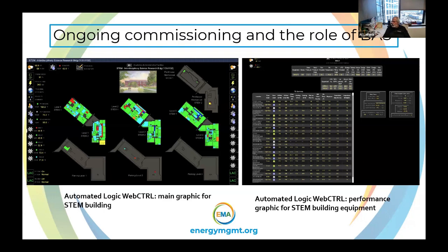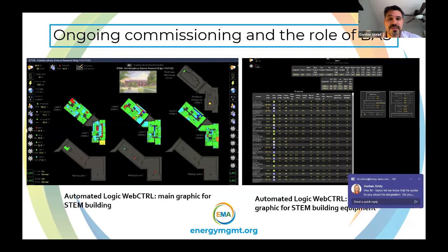I wouldn't necessarily say we have a particular routine, just for the same reason as what you said before: the sheer scale of it is enormous. I think we can say we focus on our high energy use buildings, and we're looking out for faults there. So my guys, Joe and Mike, excellent technicians, are on our BMS, BIS all the time, focusing on loops on district energy systems, but also on particular buildings, tracking down errant actuators, fixed open dampers, sensors which have gone out of calibration, sensors which have just failed, all of that kind of stuff.